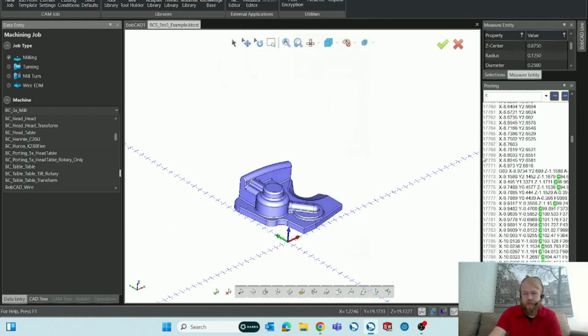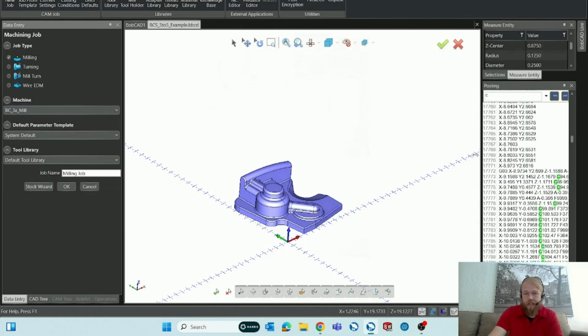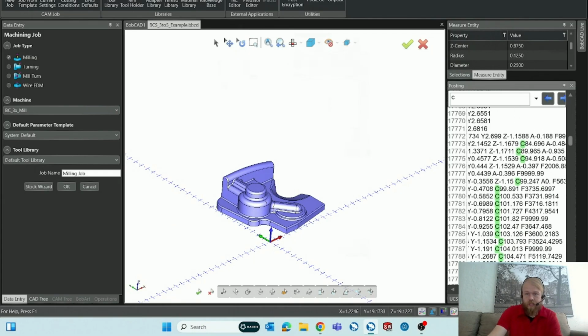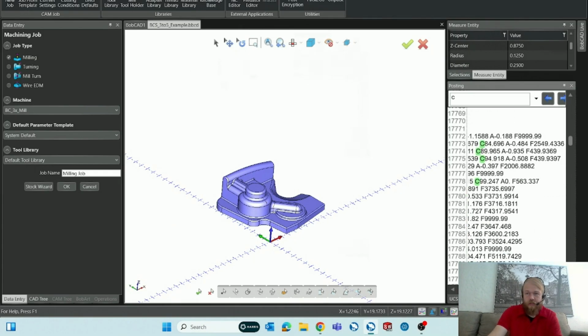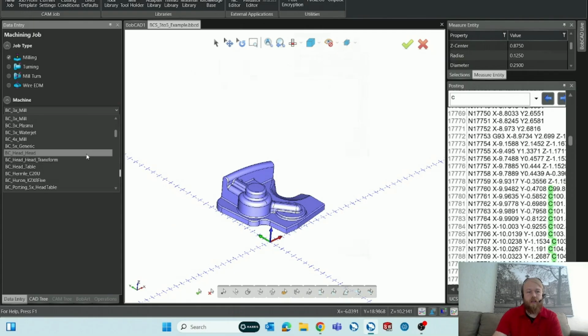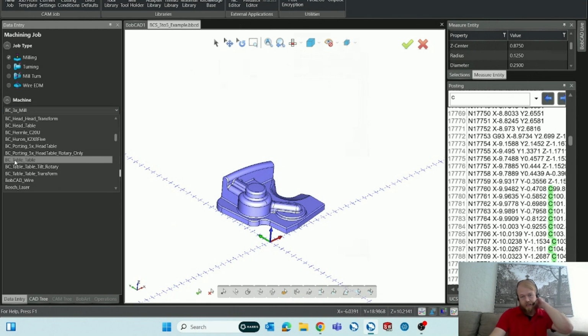You can see some of the G code that I was looking at earlier to make sure that there was some rotation of the C axis here in the G code. So the platter is going to rotate around the C axis, and then there is an A axis rotation around the trunnion of the table there. So that's our BC table. We'll be able to look at it in our simulation later.